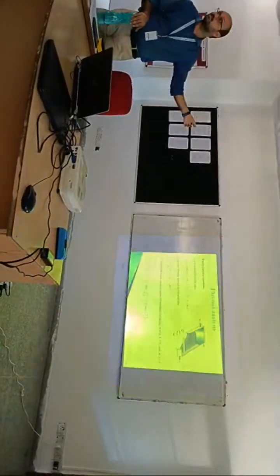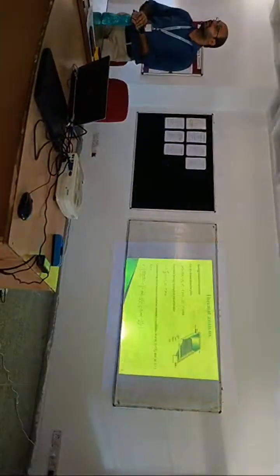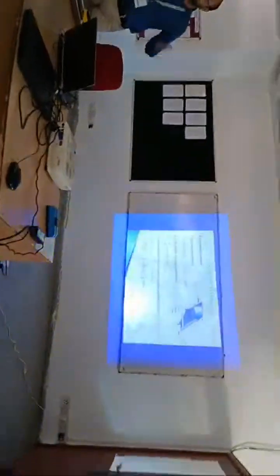On the left hand side is basically the total solar radiation reaching the tubes. This is the solar radiation, the intensity of solar radiation. Tau is the transmittivity of the glass plate. So after transmitting, this much radiation will reach the absorber. Alpha is basically the absorption coefficient of that blackened sheet. This much radiation will reach the water.